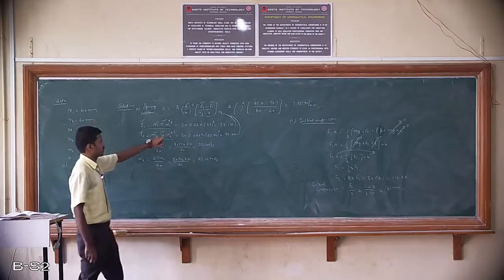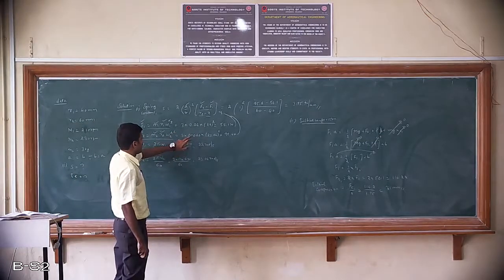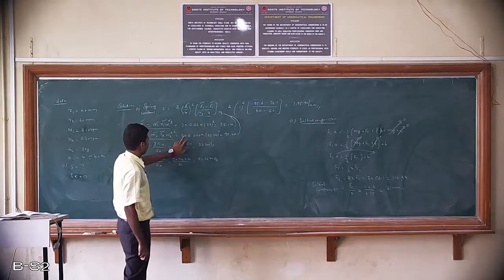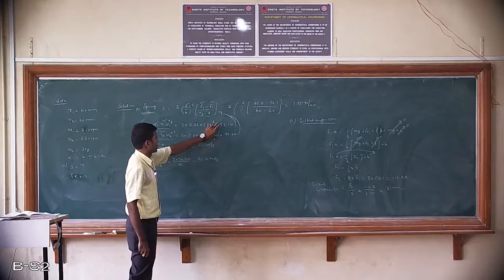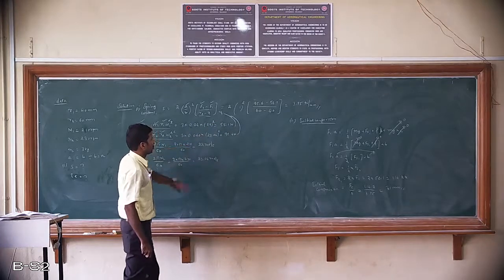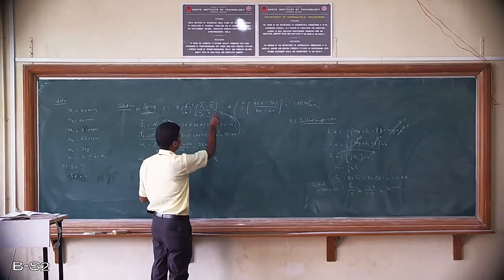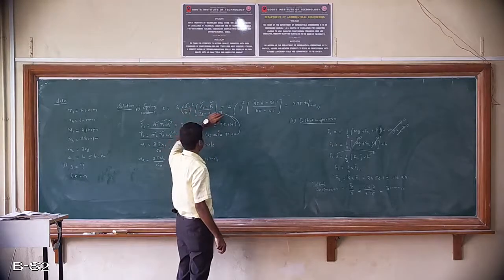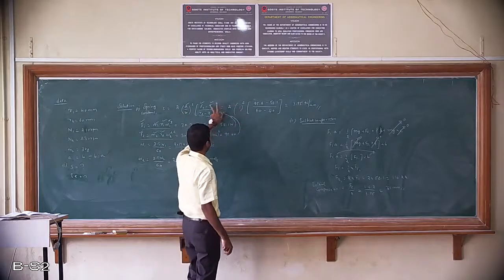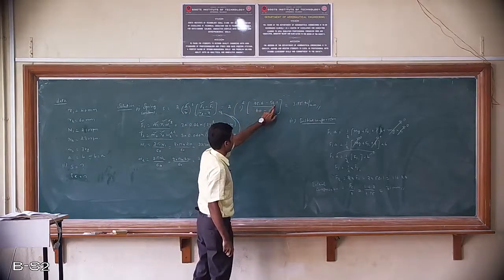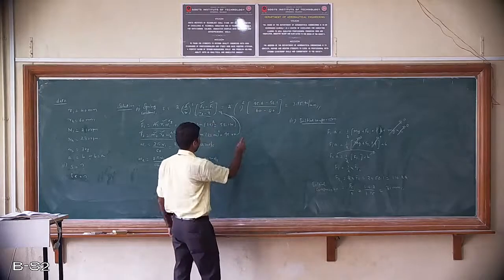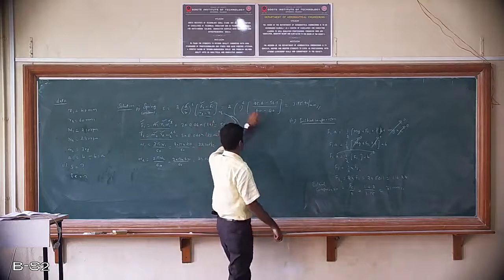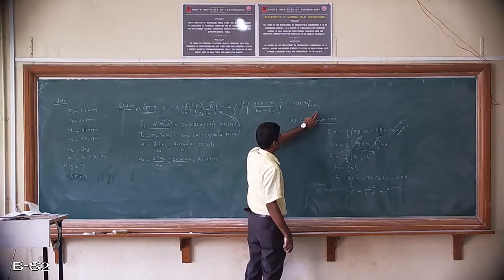I am going to substitute in terms of meters, and omega 1 as 22. Similarly, substitute the values of m2, r2 and omega 2, you get the values of f1 and f2. Now substitute these values of f1 and f2 into the governing equation. 2 into a by b whole square, as a and b are same, so it becomes 1. So f2 is 95.6 minus f1 is 58.1 divided by r2 is 60 minus r1 is 40. So I get the spring constant as 3.75 Newton per mm.